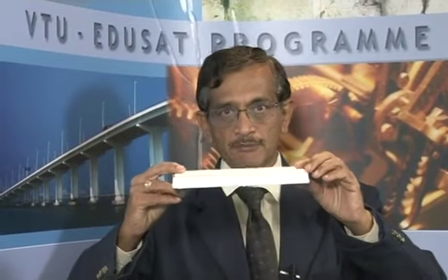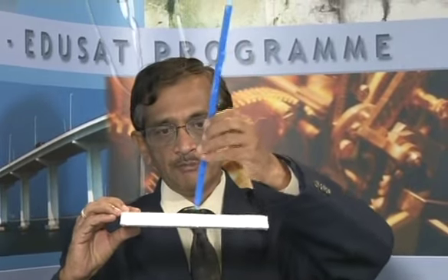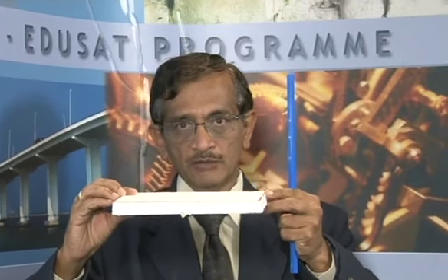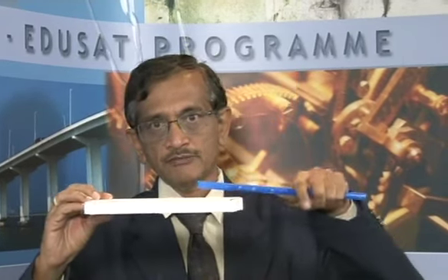Yesterday we took a problem on a plane surface. Hope you remember, we took a problem on a plane surface with a submergence in the horizontal direction, and we obtained the hydrostatic force and center of pressure for the horizontal position of the plane by using the formula gamma W into area of the plate into the depth from the water level. So, the formula is F is equal to gamma W A H bar.